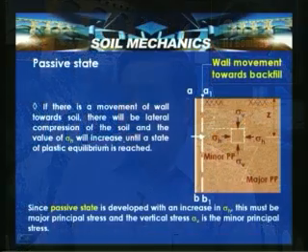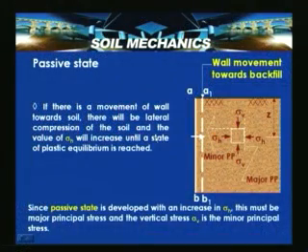In the previous case, when the wall moves away from the backfill, a lateral expansion takes place. In this case, when the wall moves towards the fill, a lateral compression takes place. So, the value of sigma h will increase until a state of plastic equilibrium is reached. Here, the wall movement is again opposed by the shear resistance along the sliding rupture plane.